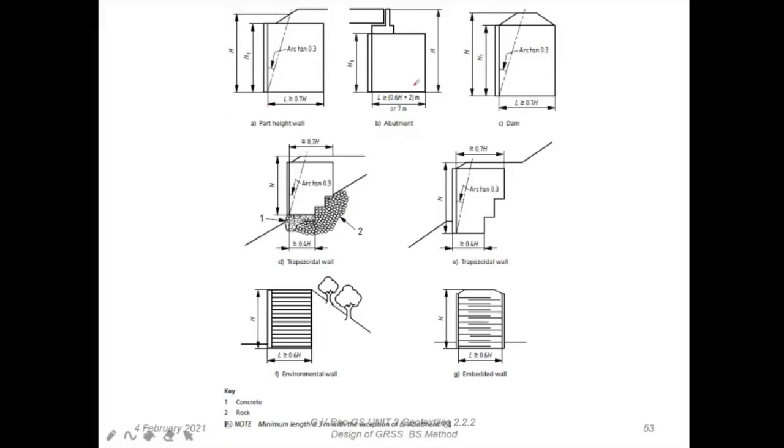In the case of a bridge abutment, where the deck slab is going to rest on the bridge seat, and this is the wall, this is the real abutment. In this case, the height is going to be from the base to the top layer here, so that is H. Again, the same values apply for a fill embankment on top of the wall. We'll follow the same system, and the height is going to be more than the actual height which you see. Here also we are going to follow the same rules. So for each of them, we have clear indications of what the design height is.